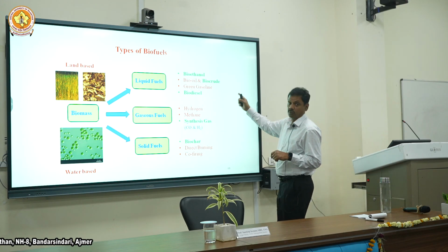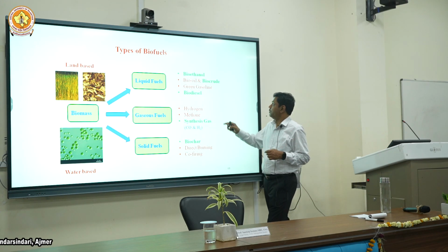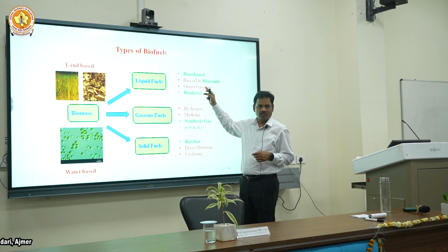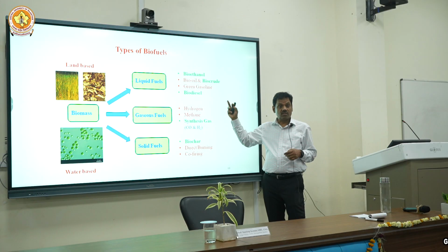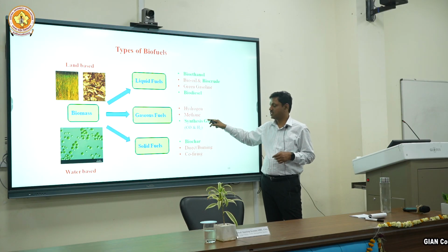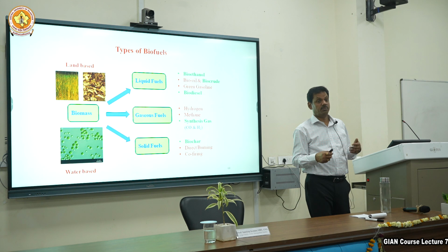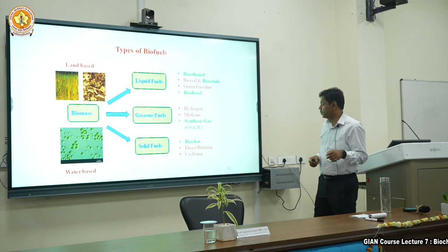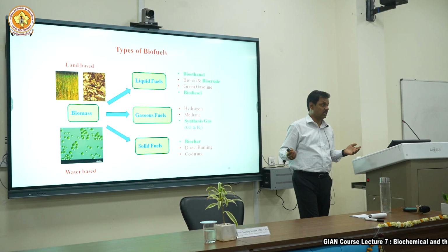All three things you can do. We can make biocrude or bio-oil; I'll show you, we have done a lot. You can do gasification and make syngas and methane at high temperature in the presence of water. You can carbonize and make biochar, or in hydrothermal, we call it hydrochar.